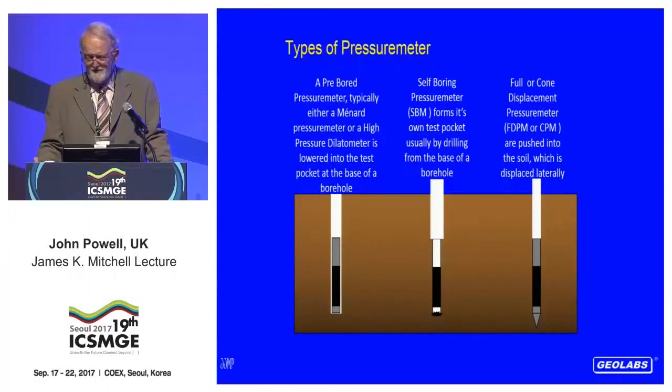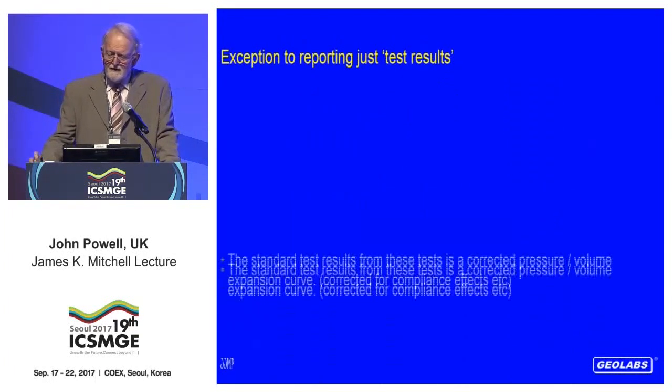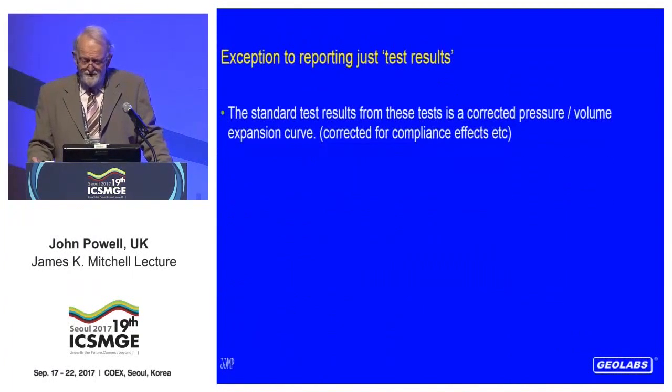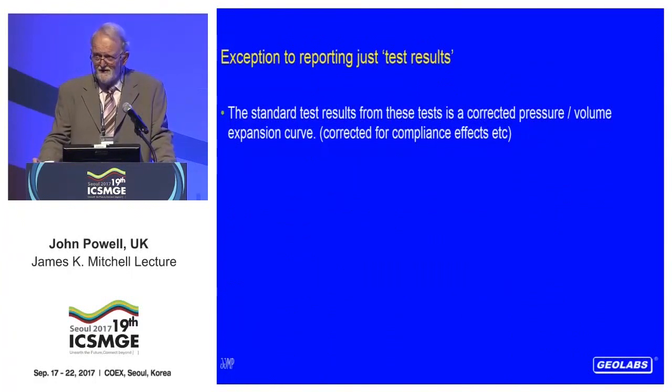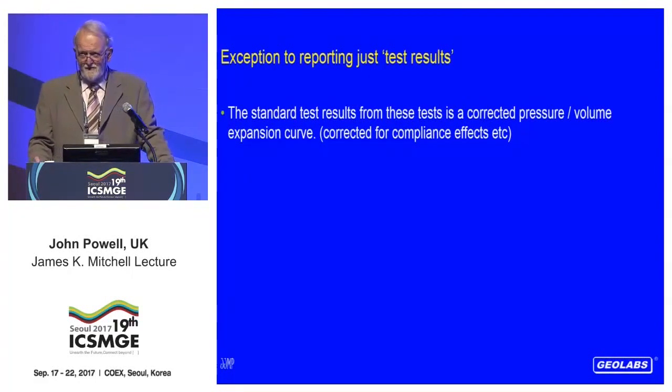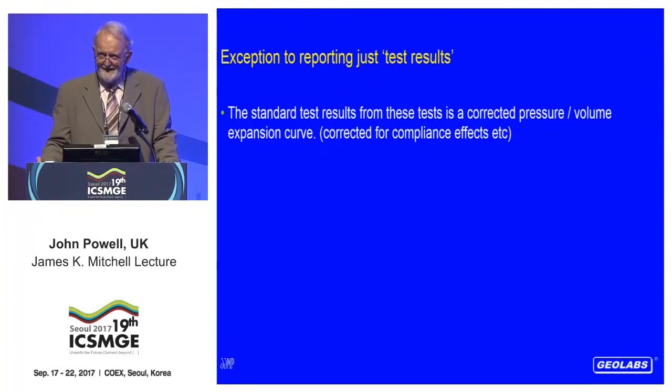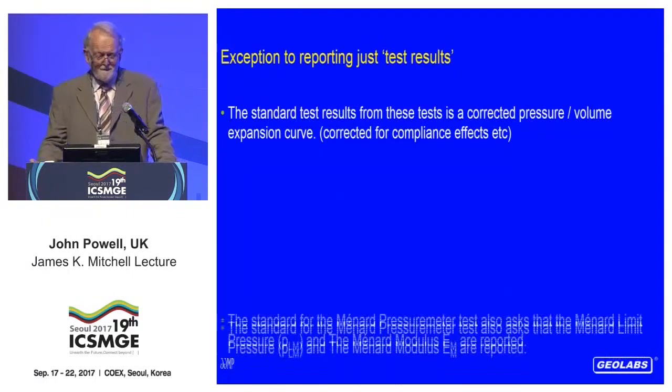3 very different types of pressure meters. Standards for these are available or becoming available. They all just report a pressure volume expansion curve, a corrected one. That's as far as the test result goes. Note I keep referring to test results because the testing standards don't give you geotechnical parameters. They only give you a test result. The interpretation comes at a later stage.